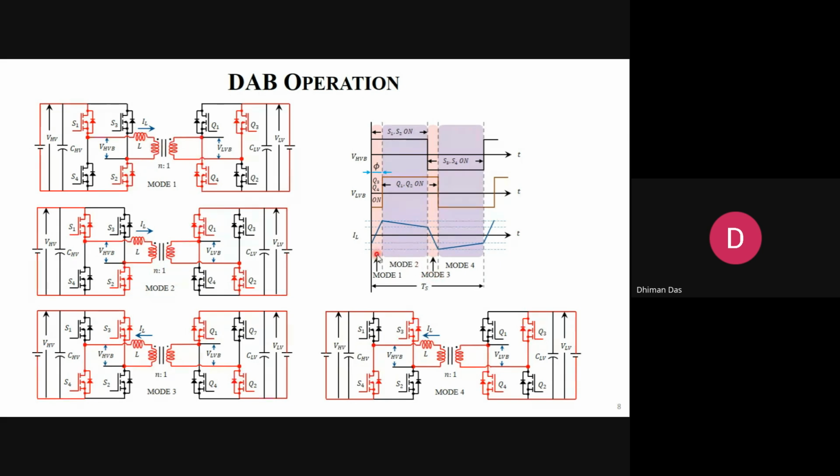If you observe any converter, any flyback converter, any full bridge converter, you can see the current rise immediately, and here it touches zero, it falls immediately. So the DIDT phenomenon is very high, because in a short period of time, dt is very small, a huge amount of current is flowing in all the traces and all the wires.